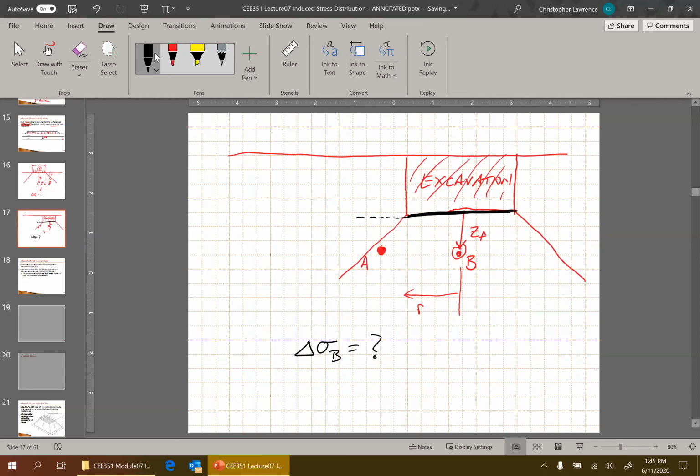The total vertical stress at point B has been reduced because of a negative influence, but even, once again, outside of its own footprint. So I think we all agreed, even at point A, there would be some negative influence caused by this excavation. The stress at point A will be less than it used to be before the excavation. Okay, that's where I left off previously.